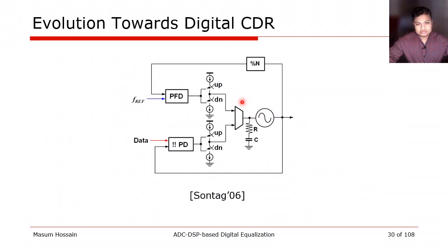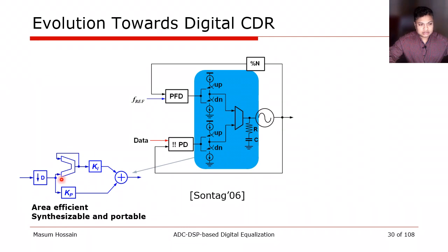So when we move to the digital domain, we can start with this charge pump and loop filter. This can simply be represented with an accumulator, a scaling factor, and a proportional path, which then goes to an adder. Obviously, this would be digitally synthesized, therefore at a lower clock rate. That mandates a decimation block or a majority voter ahead of it.